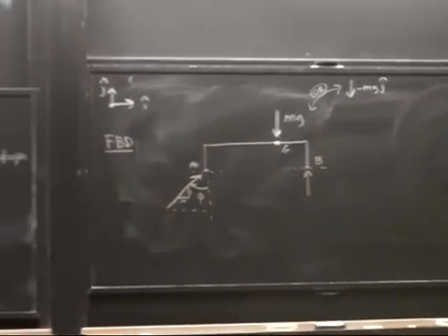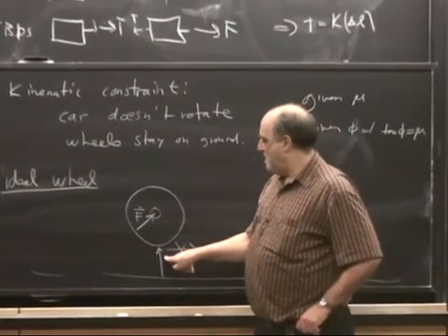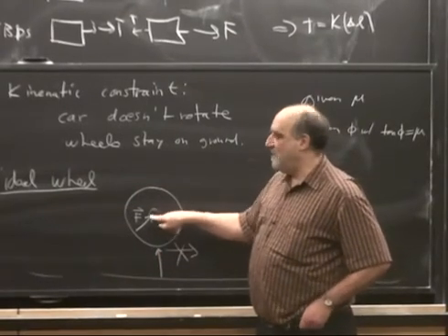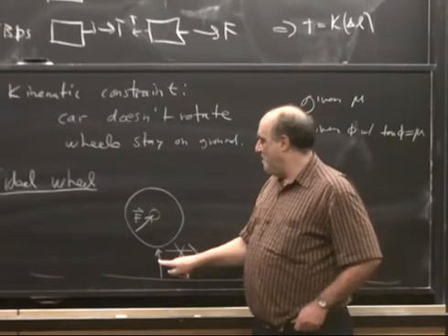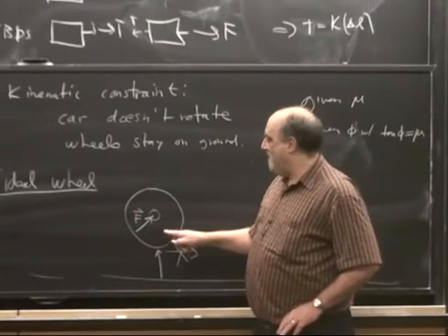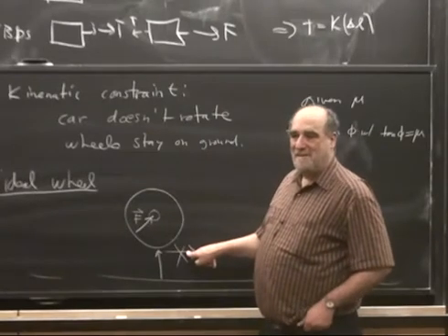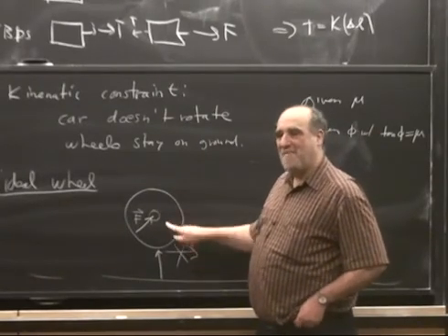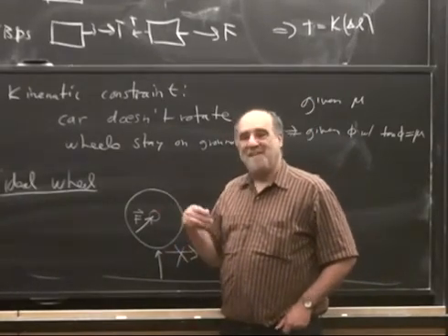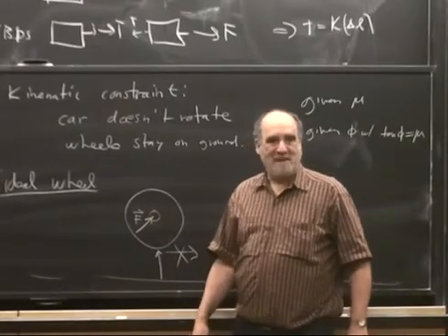Is that just the normal force that's pointing upward? That's right. I've cut the wheel free from the bearing, and I didn't show a torque here because there's no friction on the bearing. And I've cut it free from the ground, and there might be a vertical force and a horizontal force because this is rubber. And then I calculate sum of moments about this point and calculate that this thing has to be 0. If you have trouble with that calculation, you're probably thinking, oh, this wheel has a little bit of inertia. But then you think, well, how much force does it take to spin up a wheel? It's small compared to the force it takes to accelerate a car. That's negligible.